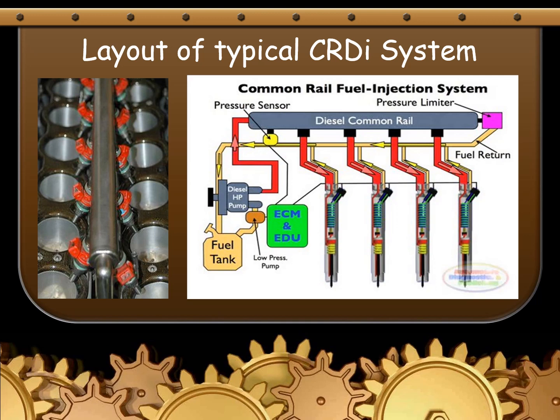Previously, the conventional fuel system used a separate fuel injection pump and a separate fuel injector. Here, only one fuel pump is used, controlled by the electronic control unit, which maintains the injection pressure and the fuel quantity. It is very helpful for lowering the emissions and saving fuel.